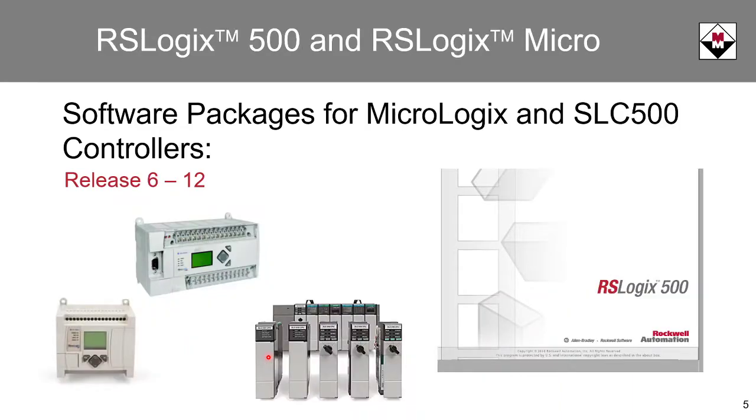RSLogix 500 is the software that can be used with SLC controllers and MicroLogix controllers. SLC part numbers start with 1746 and 1747, and MicroLogix controllers start with a 1761 through 1766 part number, with several of those being already discontinued. RSLogix Micro software only supports MicroLogix controllers.